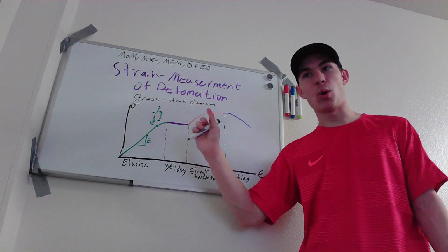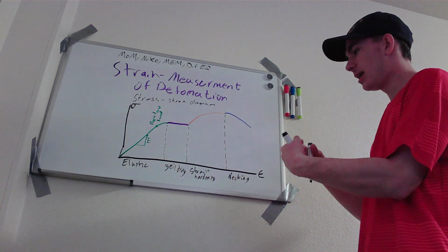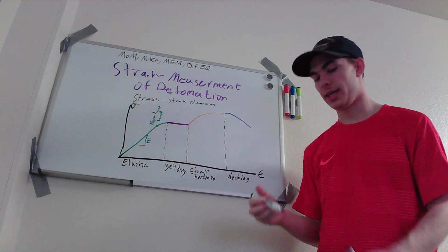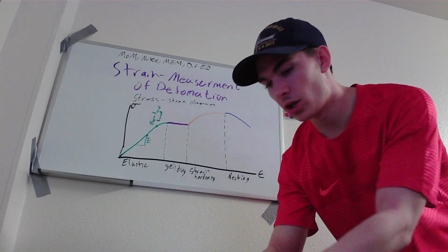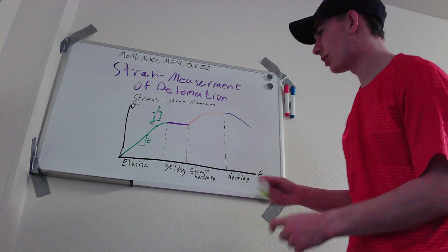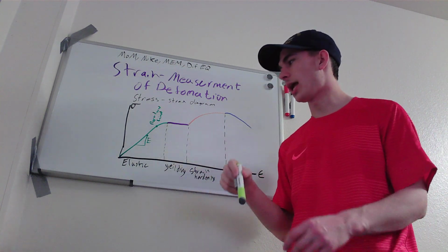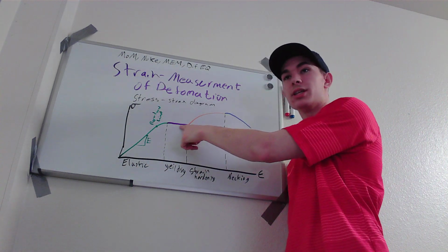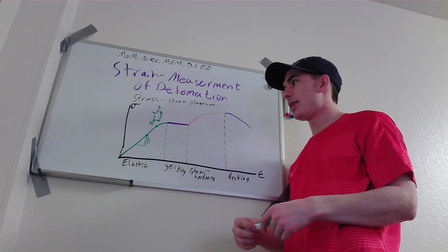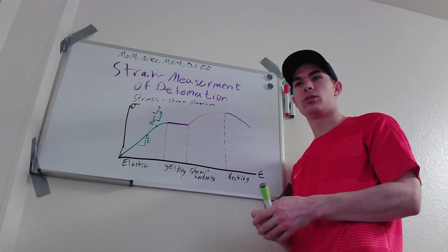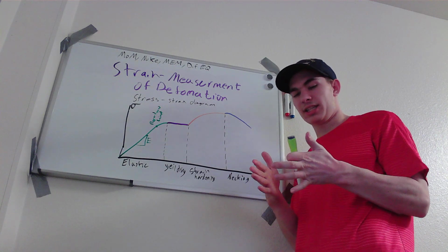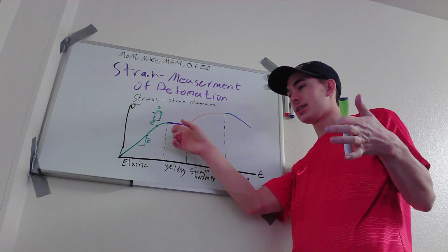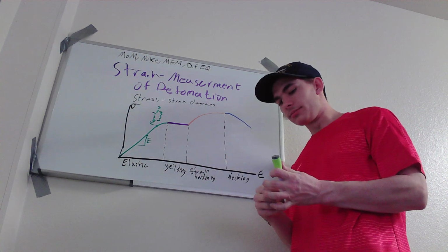Once you pass this proportional limit, then it no longer will go back to its original length. So you have this material, and you're going along, and you keep putting stress on it, and finally you're in the yielding. The yielding means that the stress isn't increasing at all. So you have not increased the stress, but it's still straining, so it's still gaining length, okay? And this is called the yielding region.